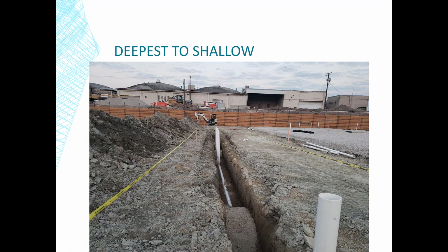But as is always, deepest to shallow, that might not be the deepest. In different areas, they'll be digging it out, and then we've got to go down even farther for more sewer piping, or garage collection drains, area drains for the garage, depending on what these are. The dewatering system here, the temporary one that's in place, is helping this get to a point where it's even workable. You can see that they're not backfilling with gravel; it looks like with some native materials to me.